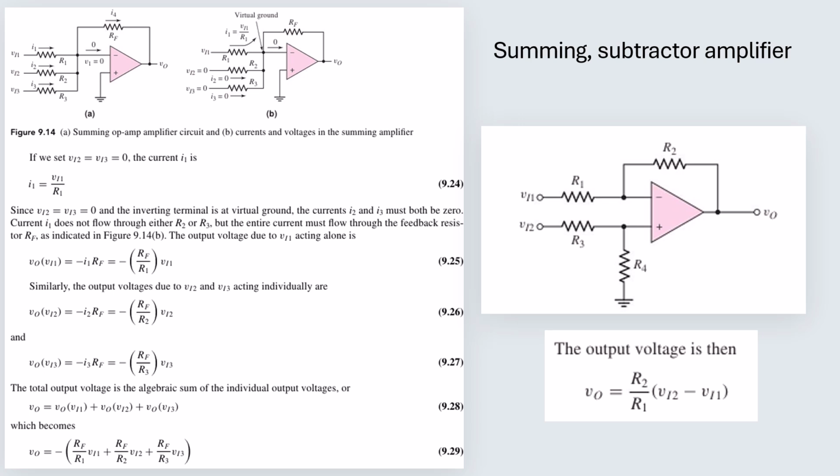So basically here you can see the summing example. Here we are using the operational amplifier, that is IC741. This is one of the applications of IC741. There are two different inputs, that is inverting and non-inverting. Through the inverting terminal itself, we are giving three different voltages, that is V1, V2 and V3. In the output, we will get the addition of all these three voltages. So this is exactly the process to add the different signals.